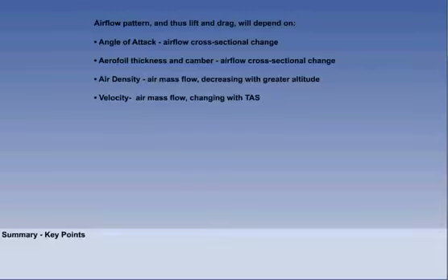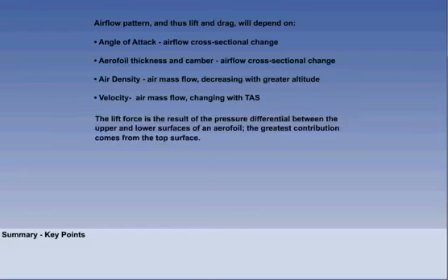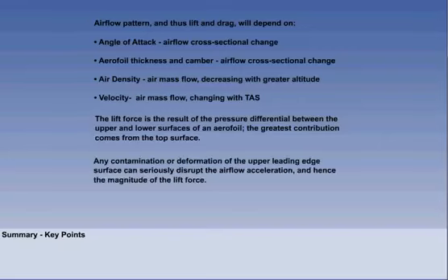The lift force is the result of the pressure differential between the upper and lower surfaces of an aerofoil. The greatest contribution comes from the top surface. Any contamination, particularly ice, or deformation of the upper leading edge surface can seriously disrupt the airflow acceleration, and hence the magnitude of the lift force.